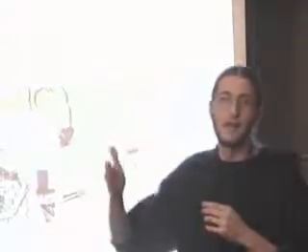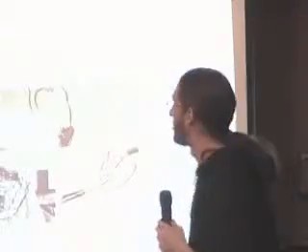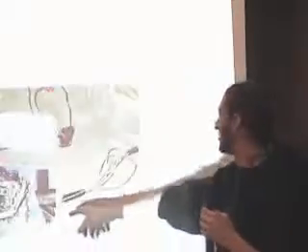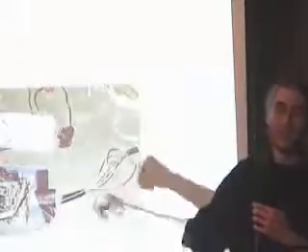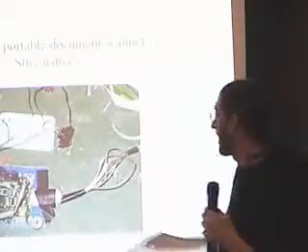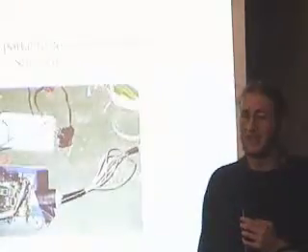What you can actually do is, there's just a gear train here. You basically hook a motor up to it, oh great, I don't even have the variable resistor in the photograph. You basically hook a pot up to it so that you can control the speed at which the motor's turning, and then you can control the speed at which the scanner is sampling, and then you can control exactly how many vertical lines it's taking over the course of time, which is just like controlling the rate at which film is moving across. Since this thing has this nice dial here, on the actual scanner, one side of this is black and one is white. So you're just setting your exposure for the scanner by turning this dial, just trial and error. Don't ask me what the ISO of it is, I never really properly figured it out.